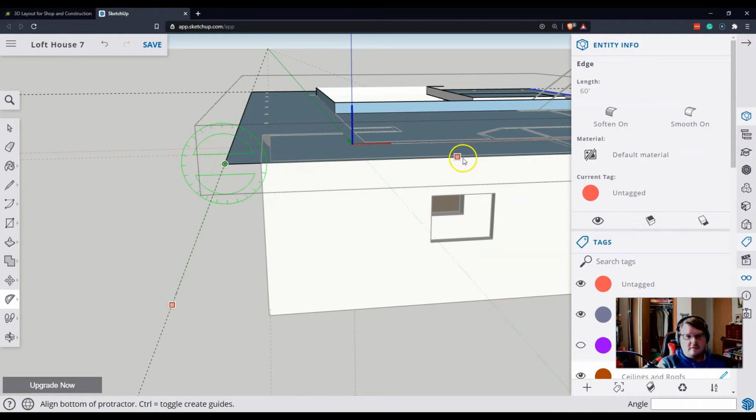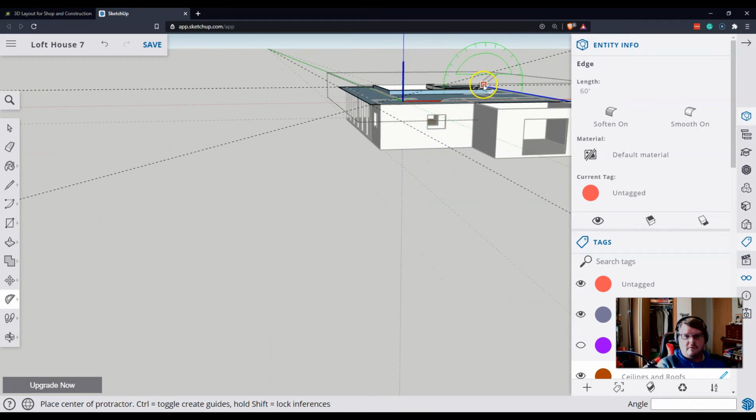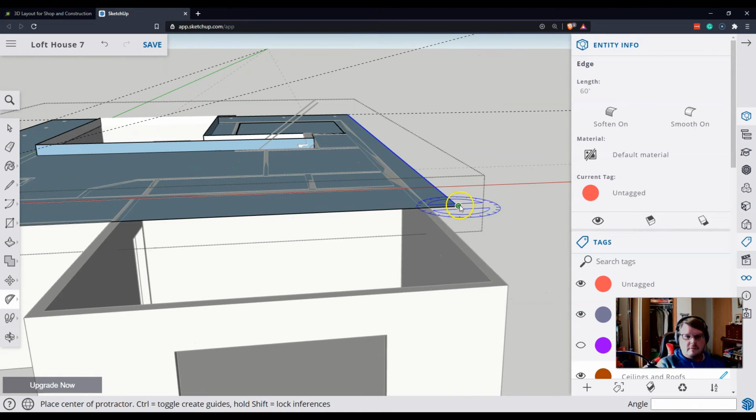Then click out to this direction because I want to pull it up from there, and now I'm actually going to make the line. Now this is a 3:12, so we do 3:12 to get that first pitch, and we'll do the same thing here. We'll pull this out along until it's green, and then click here to get that established, and now we've got our angle coming in, and this one is going to be 12.